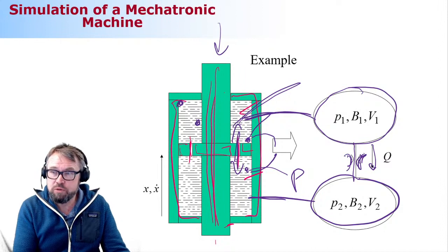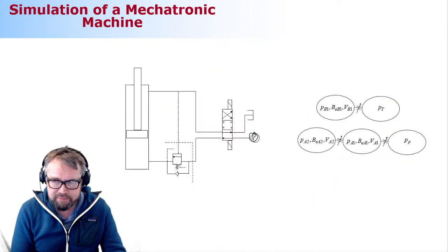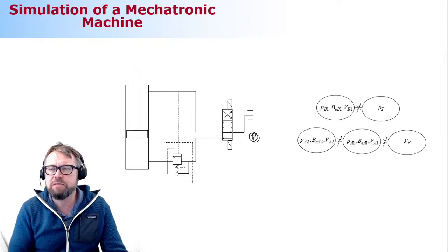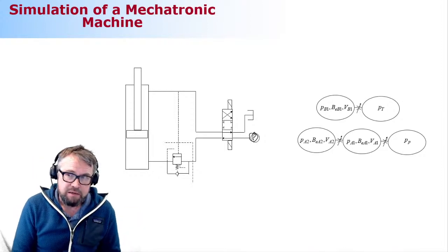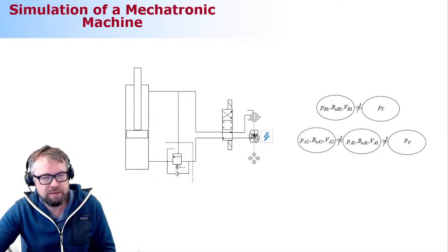So it's pretty straightforward. The first thing is discretizing. Take your hydraulics circuit, discretize that into volumes where you can say that within each volume the pressure is equally distributed. That's it. Not too difficult. Okay, so let me clear this.